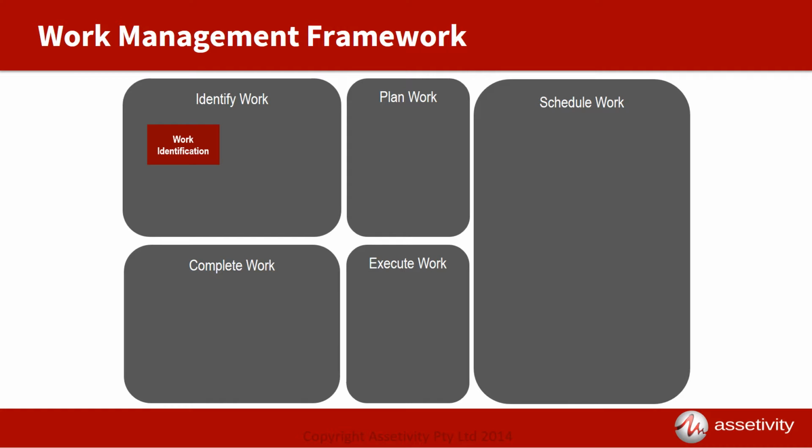The set of tasks will often include poorly defined work, duplicates or inappropriate tasks that do not align with the defined roles for maintenance personnel or the defined maintenance strategies for equipment. For example, a work request may be raised to fix a minor leak on a water pump that is on a run-to-failure strategy. In order to prevent these tasks consuming resources, we conduct a work screening process to filter them out and provide feedback to the originator.